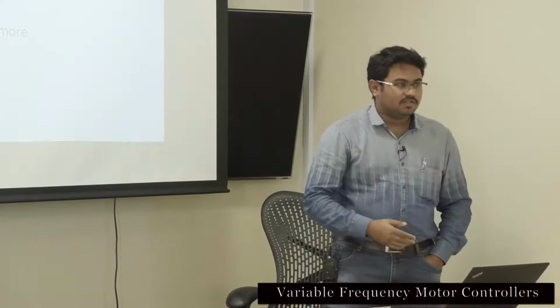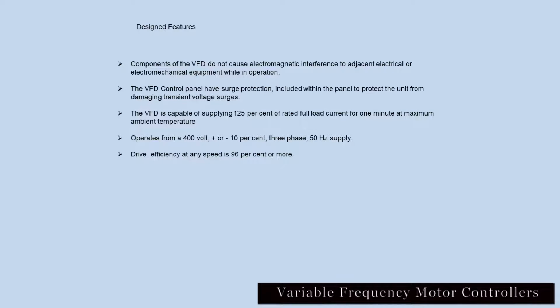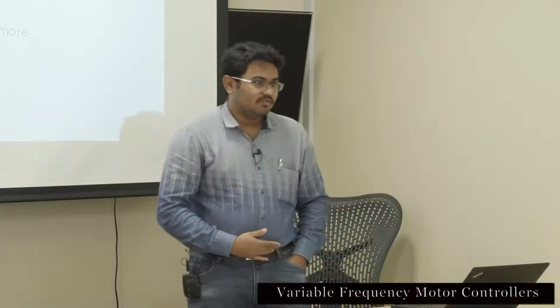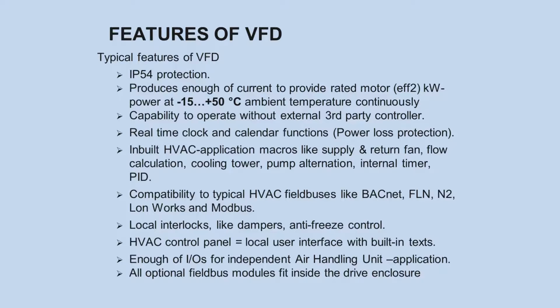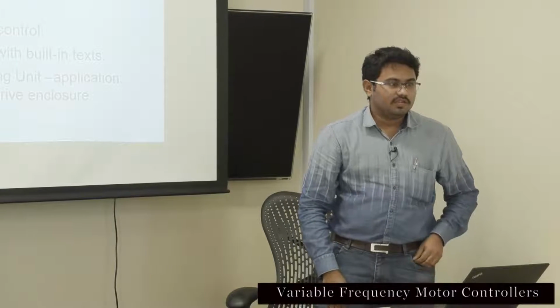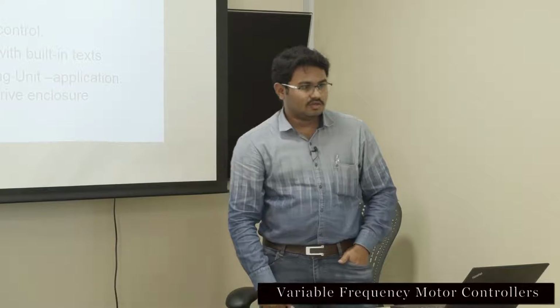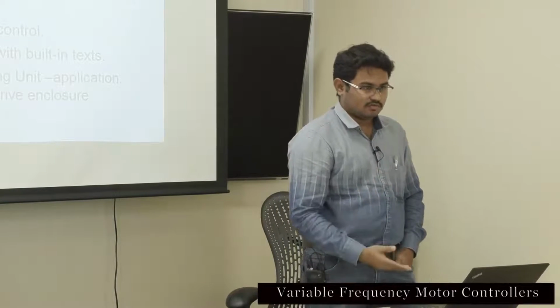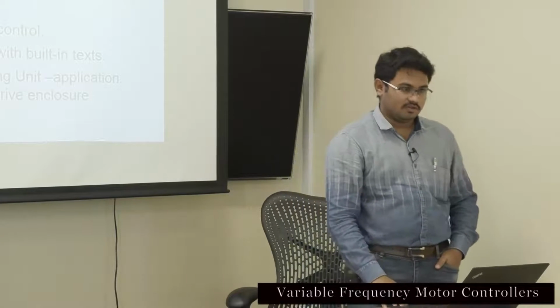And then all the drives we supply to the MTB can be loaded up to 125% for 1 minute. This is default, and it operates with 400 volts plus and minus 10%, and the efficiency of the drive is maintained at 96% all the time, and the power factor is also maintained at unity. These drives have IP54 inbuilt protection, which does not require any additional cabinet. I am talking about only the wall mount drives, not the bigger drives. Our drives can operate from minus 15 degrees to 50 degrees centigrade, and after 50 degrees we have to derate the drive current. Then we can go up to 55 degrees.